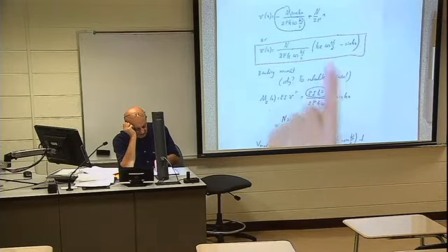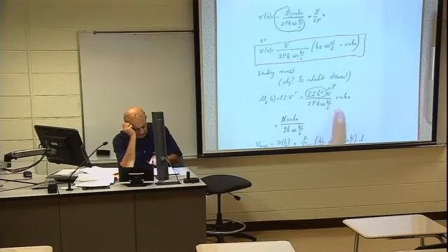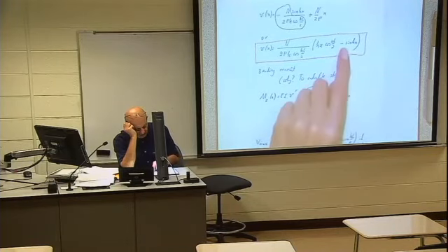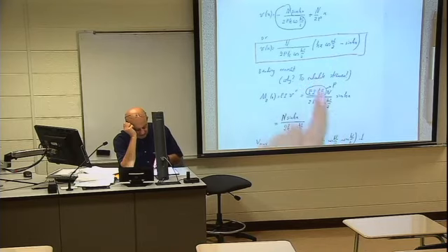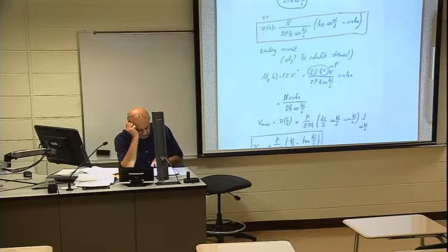The first derivative of the linear term will be constant, and then the second derivative will be 0 from here. The second derivative of minus sine kx is plus k squared sine kx. So this guy equals P. P and P will cancel. So then it will be n over 2k cosine kL over 2 times sine kx.